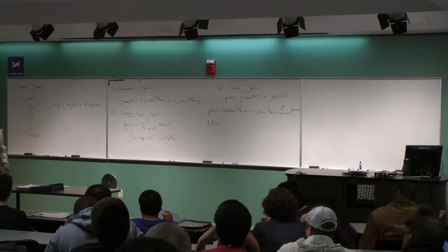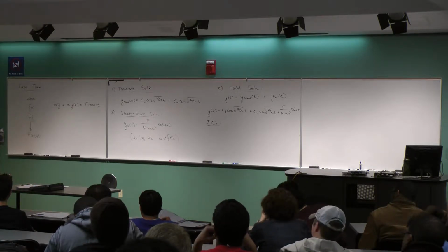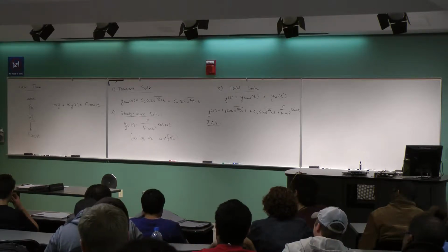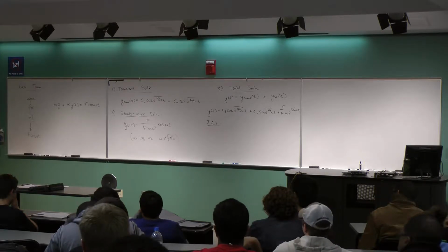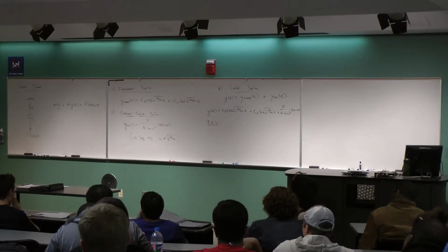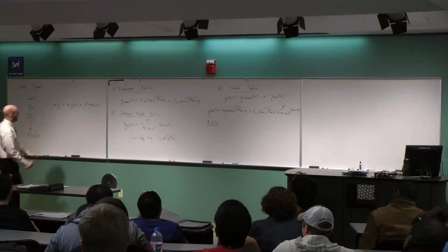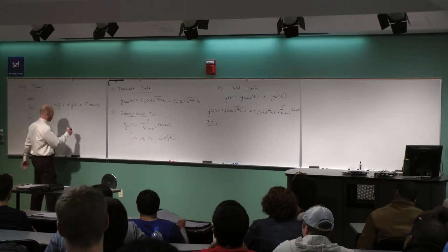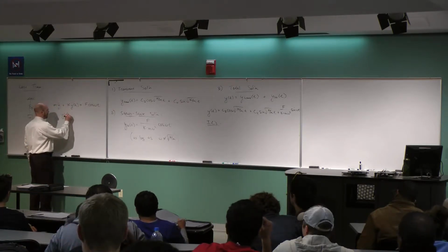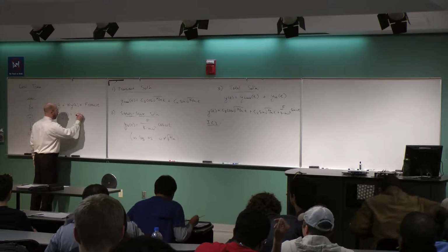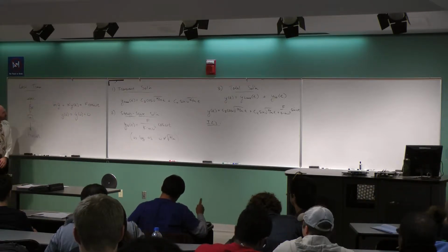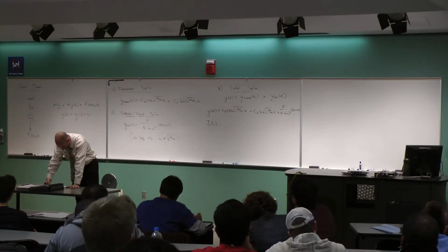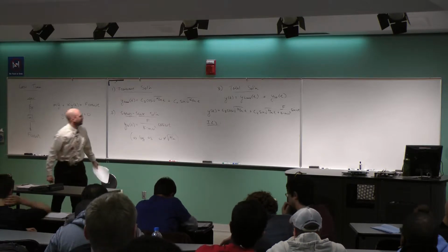So we could put whatever sets of initial conditions we want. I could apply a force to something that's already moving, something that's already displaced, but why not just go with the simplest case? It doesn't have any initial position or velocity, but it is going to have a force. The force is not an initial condition. It's built into the governing equation. The initial conditions would be starting from rest at position 0, y of 0 and y dot of 0 are both 0. The simplest initial conditions is what we'll go with because it'll probably make our life a little easier. So let's go ahead and apply those.